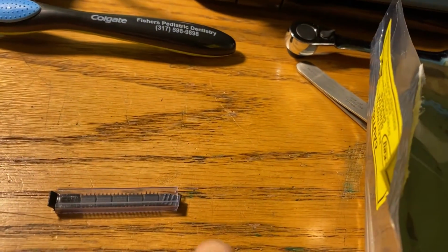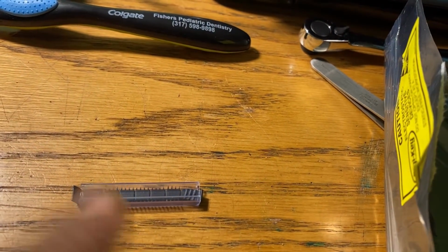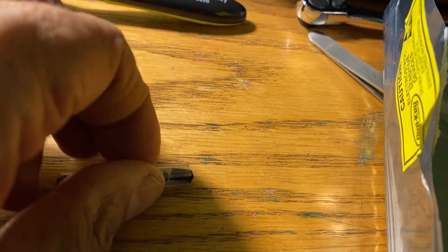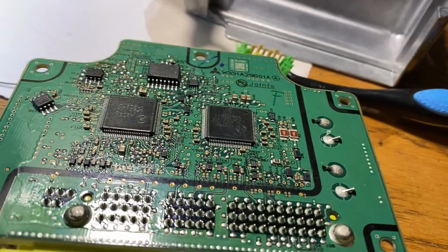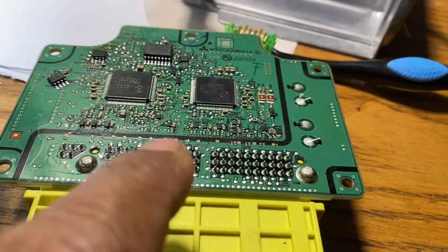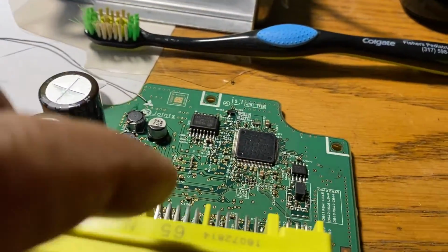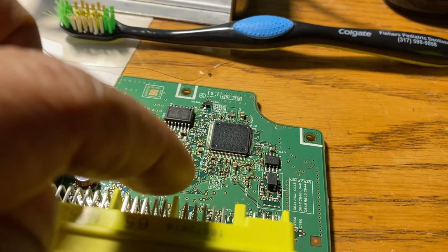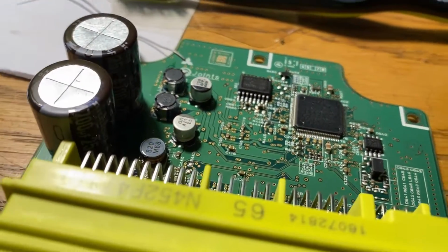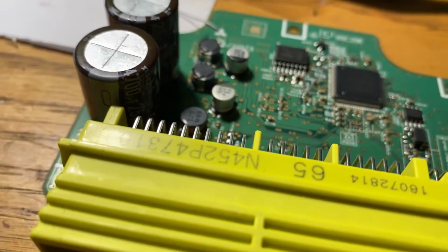You open it from the end, take it out, and then you write the clean file for the EEPROM back. Sometimes some airbag modules have a crystal, so if you have a crystal for any airbag, when you write it, especially in circuit, make sure you short out the crystal. Hopefully we're going to do this next time when we have a chance.